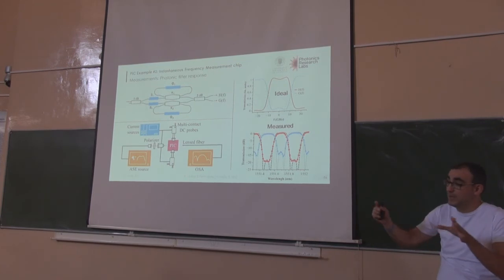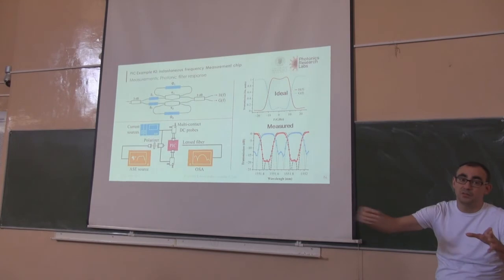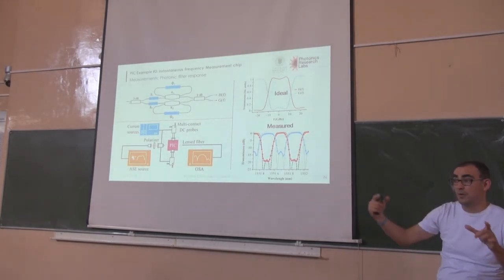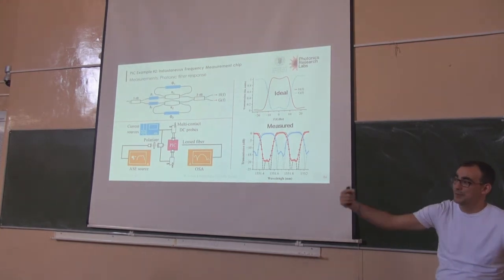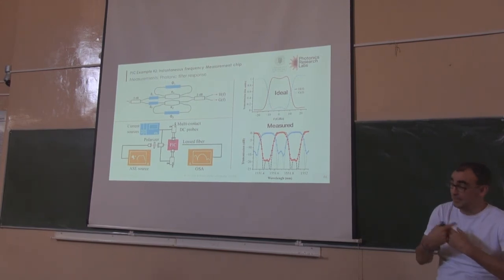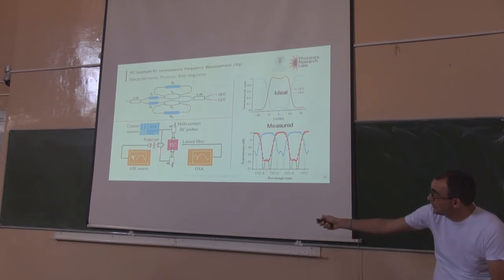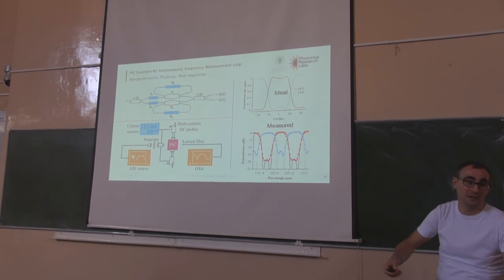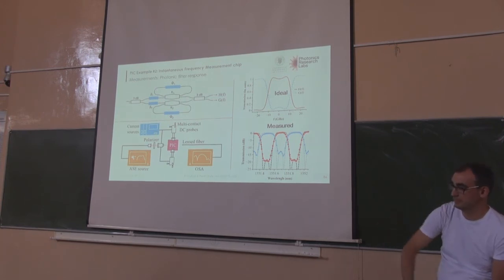For this filter we had access from the outside of the chip, so we could measure the transfer function. For the other one, we didn't have access, so we actually don't know how well it was, because we could not measure it externally. We had the polarization rotation issue. My feeling is that it was as good as this one, but with the polarization rotation, we had issues. In this case, since we are using polarizers at the input, everything is going well. So you can trust design and fabrication of these things from our experience.